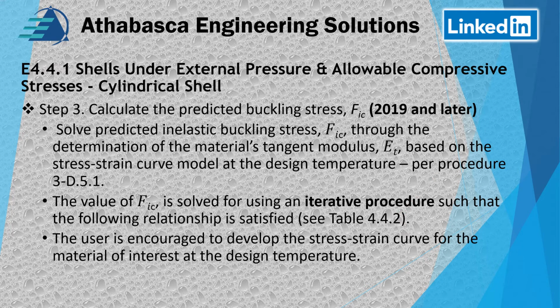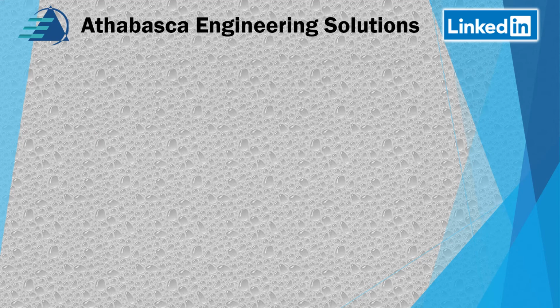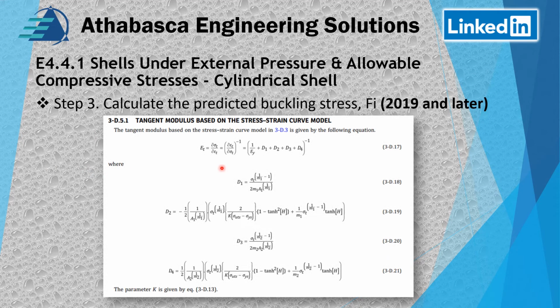So I'm going to show you roughly what these equations look like, because they're quite intense. You can see them here. Instead of these simple ratios, now we've got this, and then we basically have D1, which you put in there, and in here, and in here, and M1s, and some of these factors are found in tables, but you're having to assume your true stress and iterate using that one for this equation.